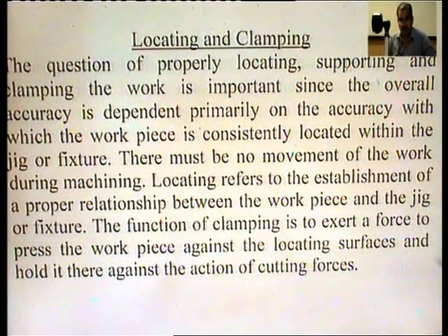The question of properly locating, supporting and clamping the work is important, since the overall accuracy is dependent primarily on the accuracy with which the workpiece is consistently located within the jig or fixture. There must be no movement of work during machining.